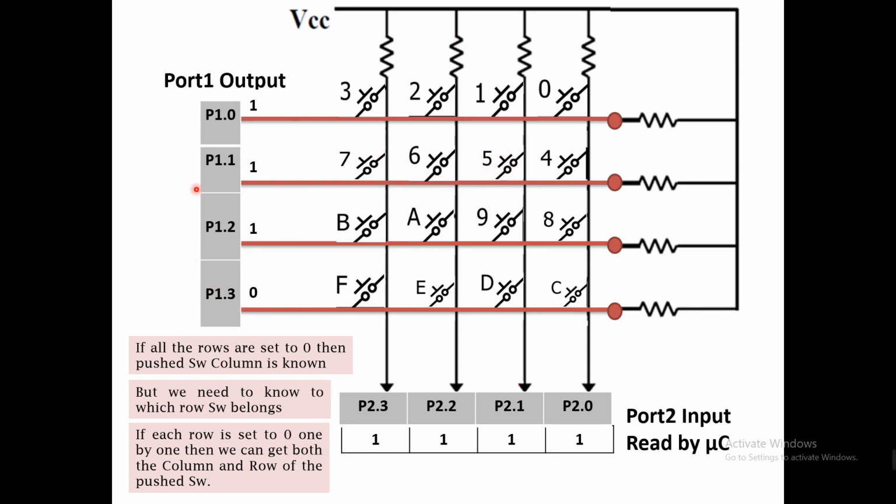Scanning time is maybe 10 microseconds, but the switch will stay pushed for at least 5 milliseconds. In this duration, the microcontroller will make each row 0 one by one and will know which switch it is. This task can be performed in a few microseconds, so there is no time issue.